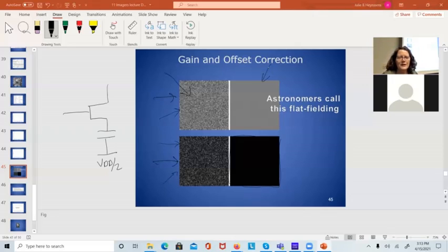Okay. What we did is we couldn't turn reset off. So I started looking at this and saying, okay, we need to get a really long decay time on here. And this goes into the sense amp and compares it to VDD over 2, the pre-charged line from someplace else. The first thing was I'm just going to power it down and see what state it reads up in. And I got a whole bunch of nonsense that just varied all the time.